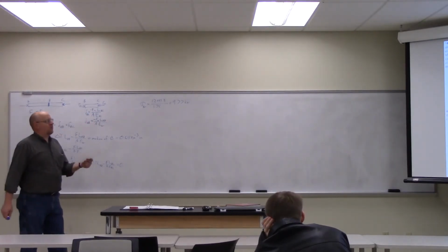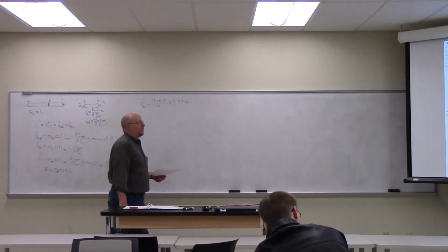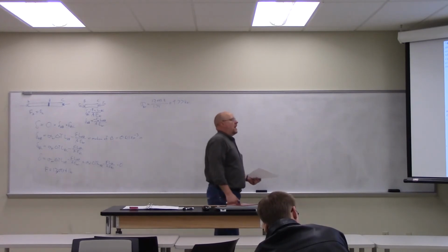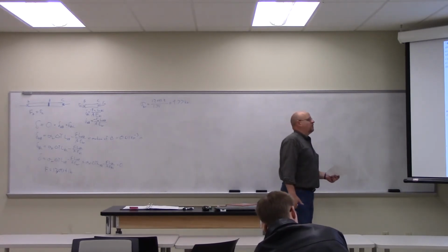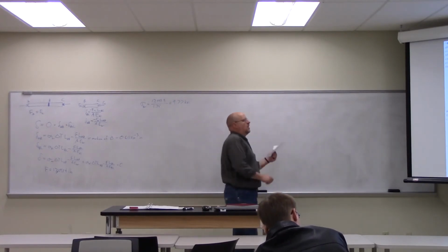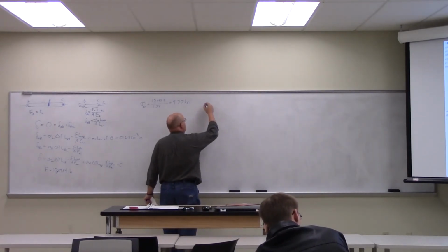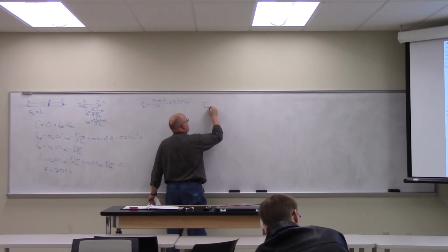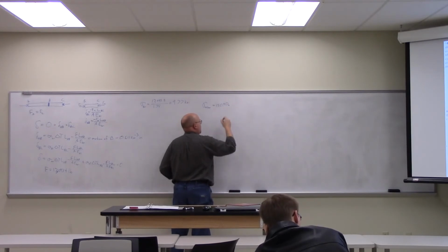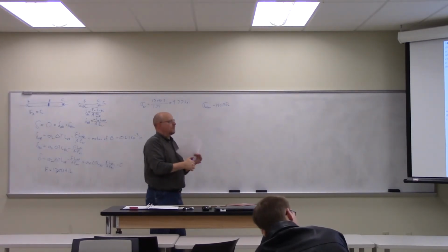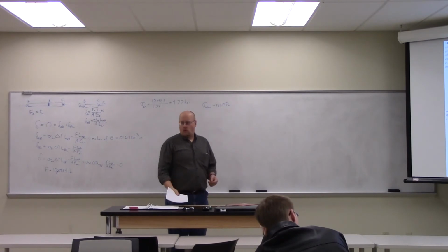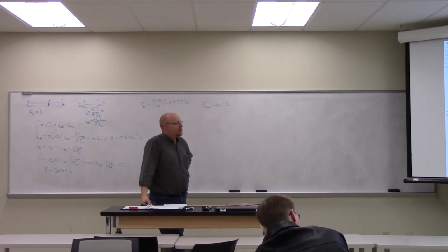Okay, let's real quick try to run through at least a little bit of 489. With a steel bar with the dimensions shown, determine the maximum axial force P that can be applied so as not to exceed an allowable tensile stress of 150 megapascal. So the allowed tensile stress is 150 megapascal. What's the first thing you're going to do with this problem? And it's not a free body diagram.